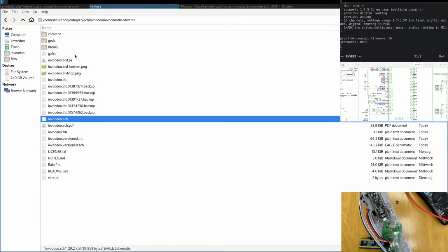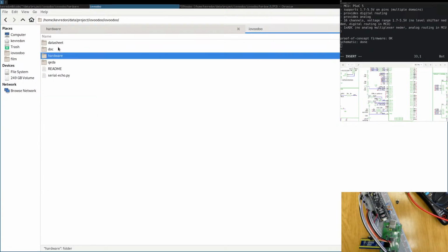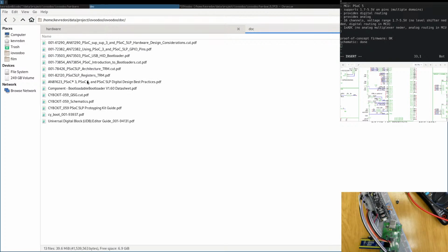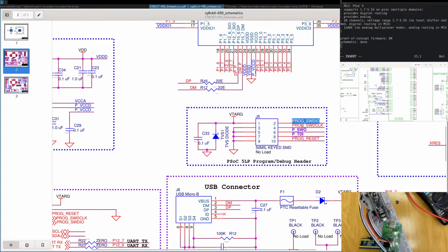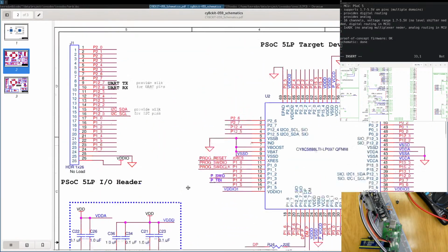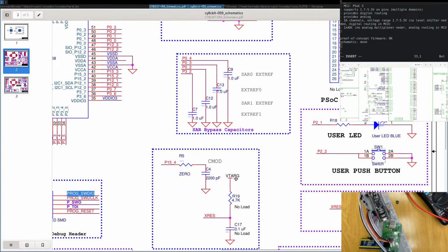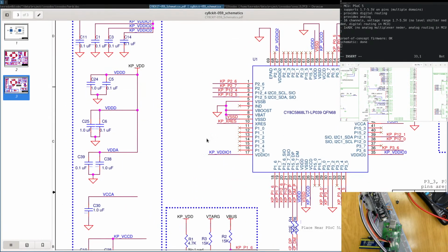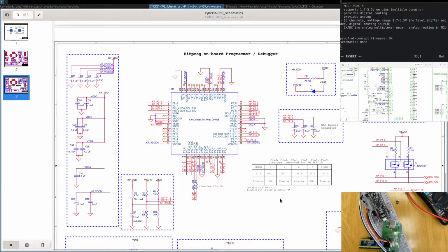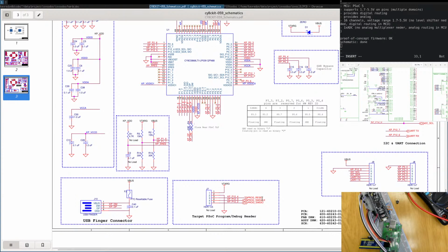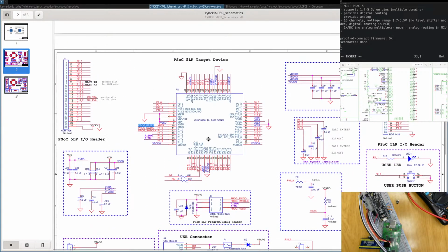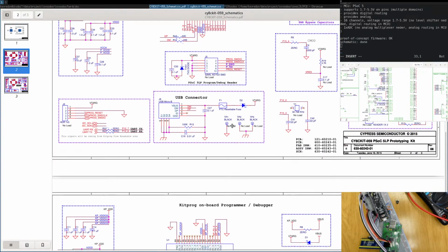Does their board do that? The schematic. So this is the development board. No, they don't. No, this is the wrong program. Where is this side? This is a KitProg. There is a connection. Yeah, this is the header, and this goes to ProgReset directly. ProgReset, yeah, they don't put any inline resistor with SWD IO.